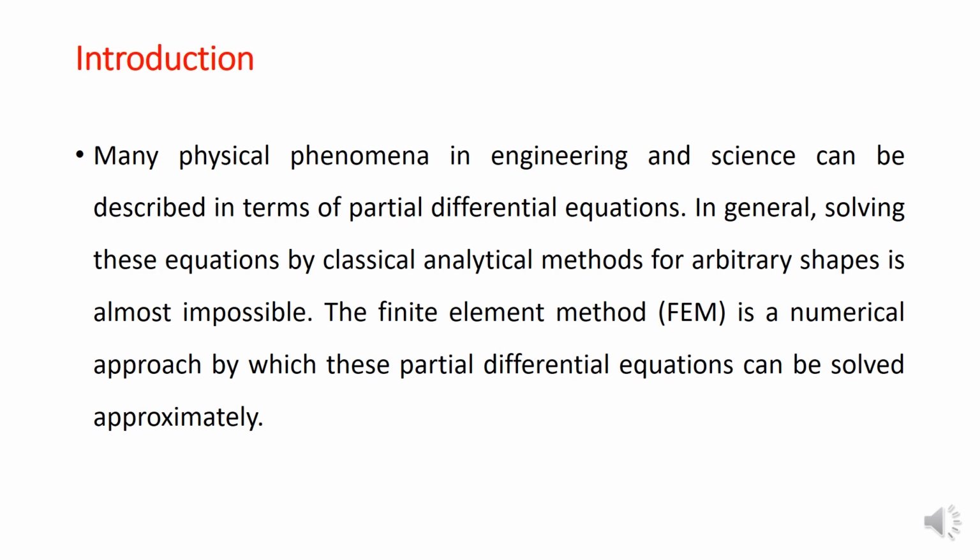So basically, the finite element method is used when you want to solve problems which relate to some complex shape or arbitrary shape. When you want to solve problems on these complex shapes, you might have to divide the complex shape into a finite number of elements. So we will divide the entire geometry into a finite number of elements, then solve for each individual element, then combine all these elements together. That will get you the result, or solve the problem on the complex geometry.